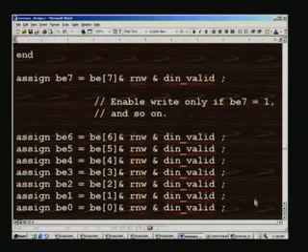Prior to writing, this writing is going to happen through the PCI bus. Another PCI master, such as a video grabber we have seen earlier, will be writing into this core straight away, and this will be housed in the video codec that we have seen in the earlier example. We have also seen in the block diagram at the start that BE7 through 0 is used as part of the PCI signal. This is a PCI signal straight away.